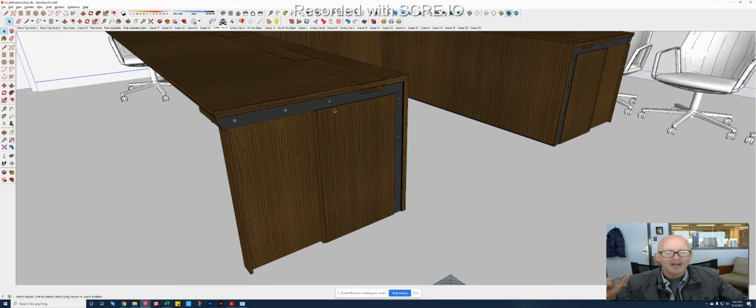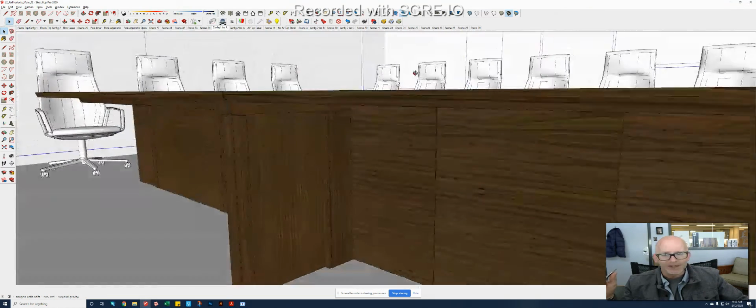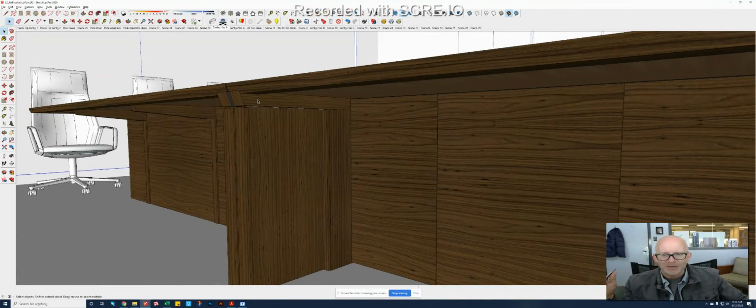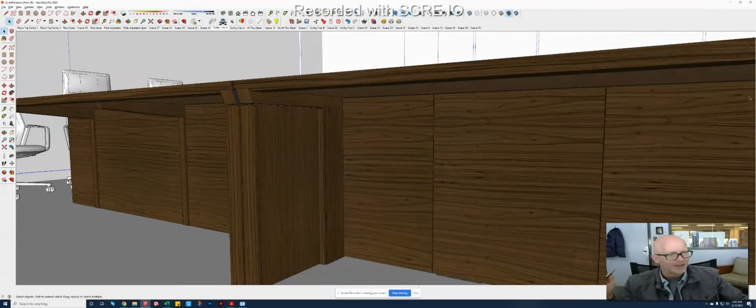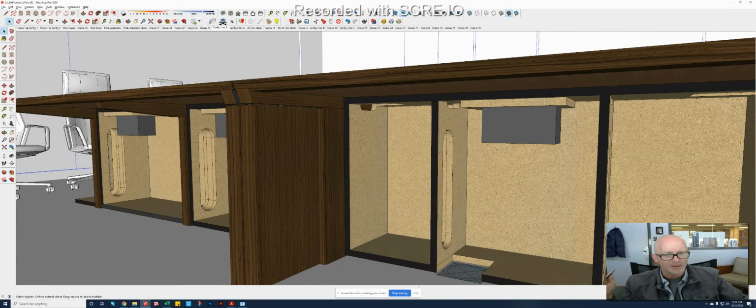So you basically take off those covers, and what that does is it exposes a series of inserts and also a wire run. When you put the modular section in place, you will have fasteners, bolts, 1, 2, 3, that will go through some small openings to connect directly into those inserts. You'll open the doors here in the base, and again, there'll be fasteners along that front edge.